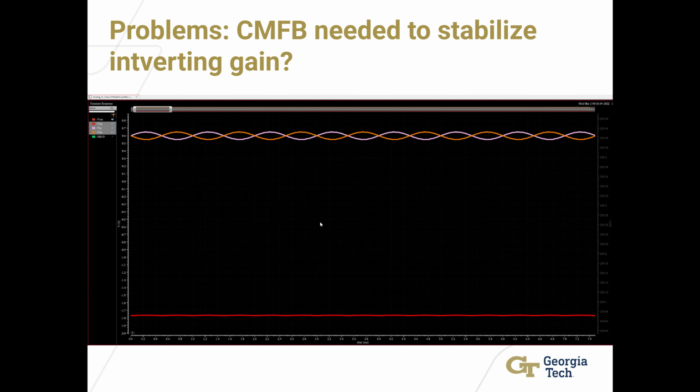But we think this will provide enough gain if we relax on our settling time, our dynamic error, and our static error specs a little bit. So that's our plan for the next week: to relax on our spec for dynamic error and static error, and then recalculate some of our values so that we can see if we can get enough gain out of the diff pair plus the active load.